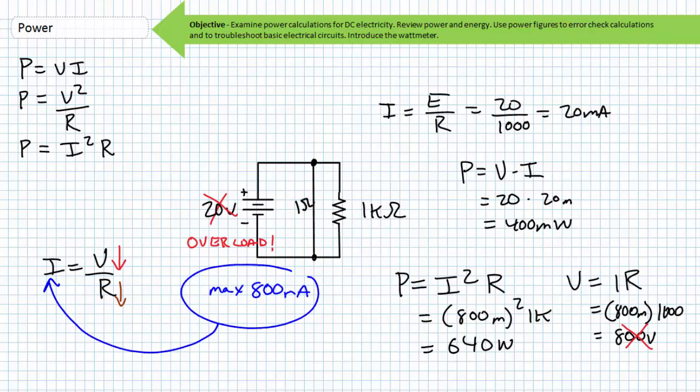The total resistance of a parallel combination of a 1 ohm resistor and a 1 kilo ohm resistor is, for all intents and purposes, still 1 ohm. Using the idealized combination of these two resistors in parallel, we realize the source is only seeing 1 ohm of total resistance. What's the voltage necessary to draw 800 milliamperes with only 1 ohm of total resistance?